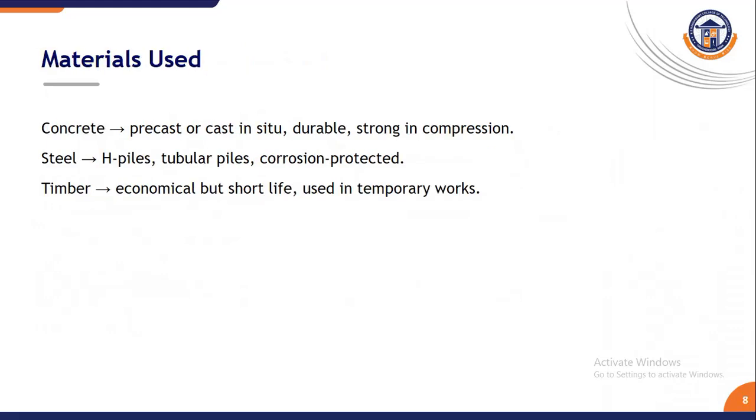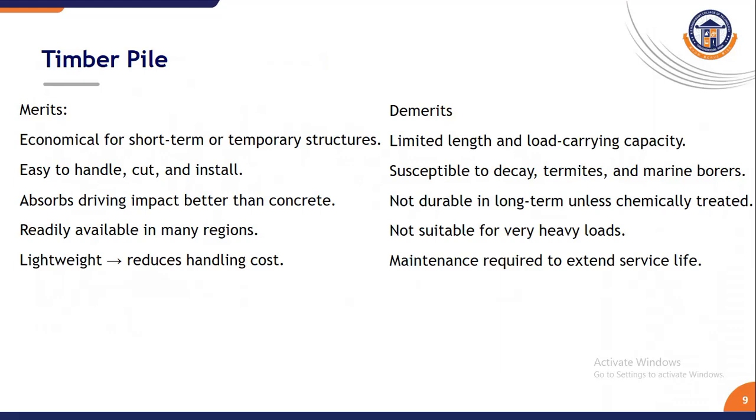And also timber pile has merits and demerits. Merits of timber pile are that it is cheaper, lightweight and easy to handle, which makes it useful for short-term projects such as temporary river crossings, right? They also absorb the impact of driving better than concrete piles, reducing the risk of damage during installation.